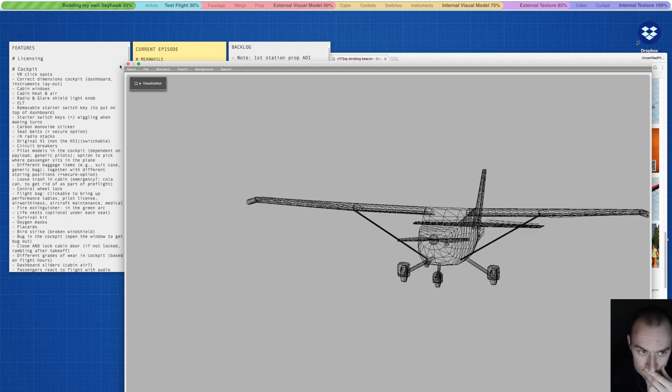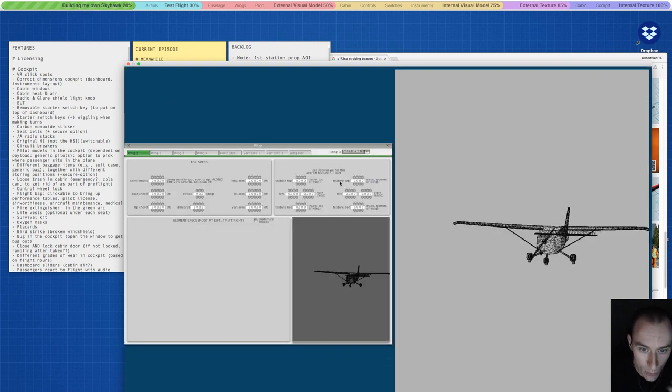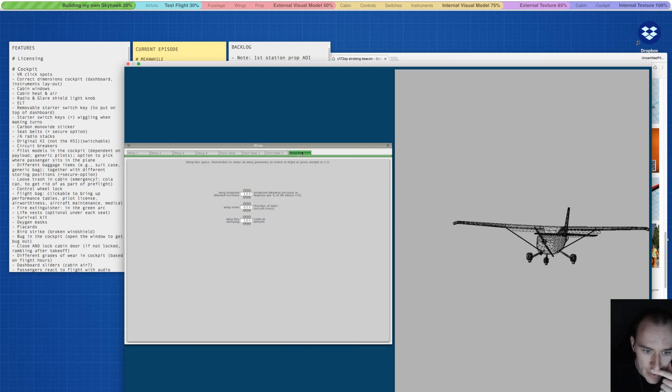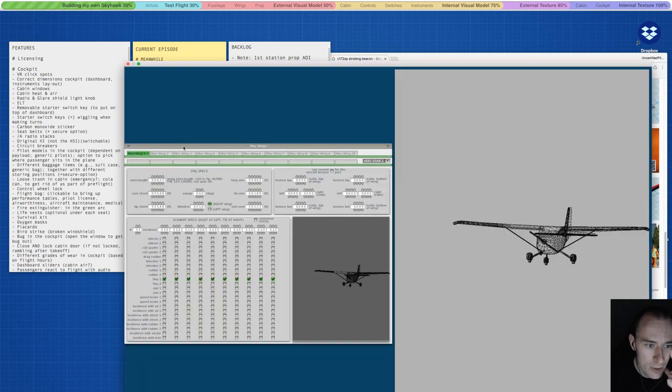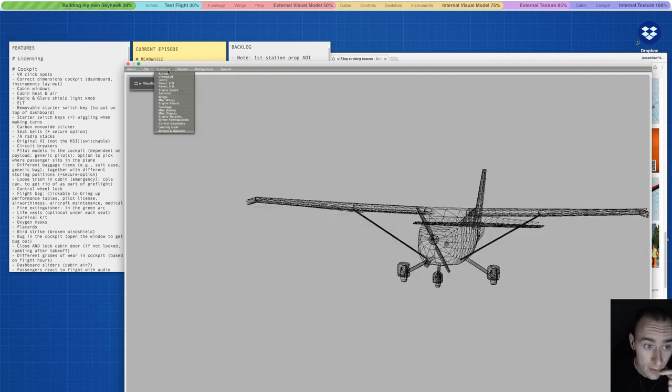Okay, yeah, systems we checked. Well, wings we made. We did miscellaneous wings because we knew they were not symmetrical, at least laterally. So in terms of dihedral and stuff, which makes our model not able to do wing flex stuff, which in the 172 is negligible, I guess. So miscellaneous wings, here we have it. Flaps, all of that stuff is good. Angle of incidence is 2. Much more precise, so that's awesome.